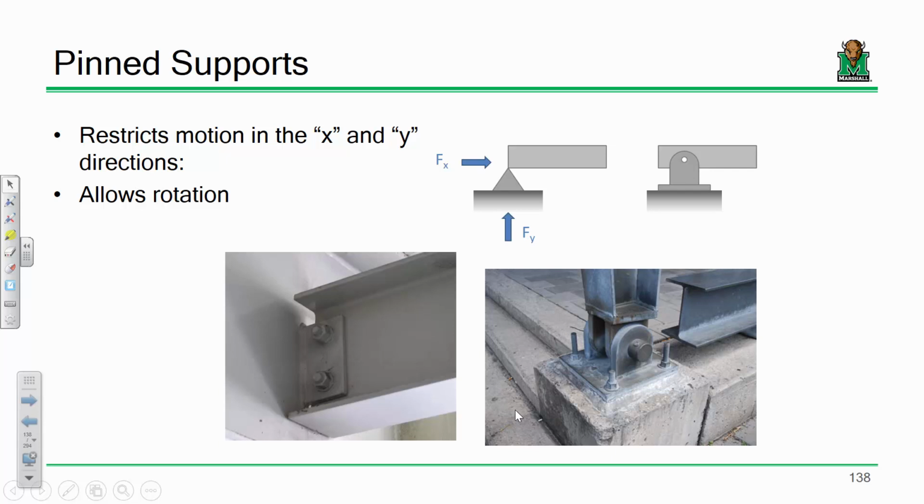But for you civil engineers, we idealize this one on the left as a pin condition as well. And you think, well, now hold on, you've got 2 bolts on the end of that beam. That's going to resist that bending a little bit. The answer is, yeah, but not very much. And this is one of those statements where you're going to have to trust me, because later on we're going to derive these formulas.